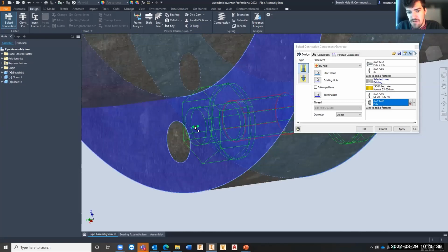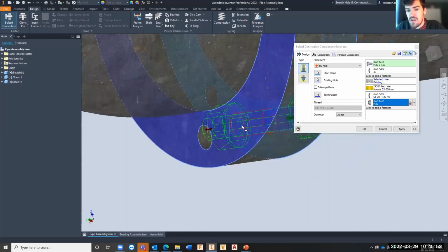It's giving me the two arrows here where I can actually adjust the size or the length of my bolt. So if I wanted a bit more room, just for future expansion, maybe you want to add a gasket or some other bit of material in the middle, or just have some room to play with, you can always come in and add length to it, and you can see how the value is now changing. The designation of the bolt itself is changing inside of our list over there.